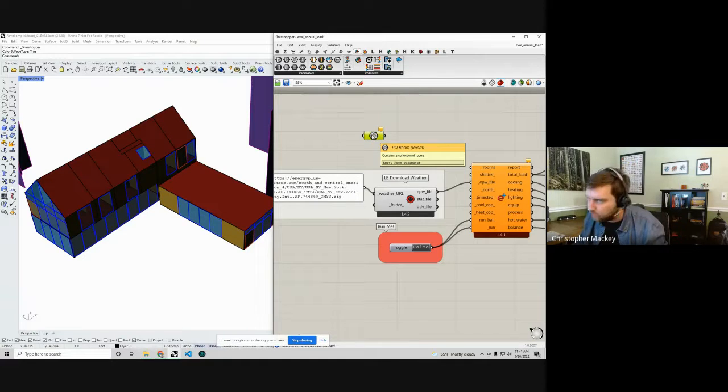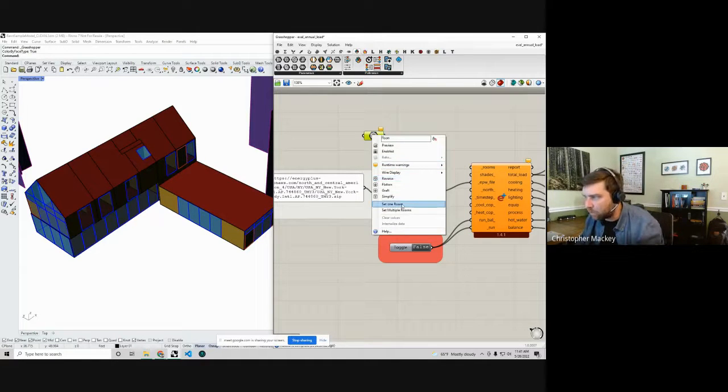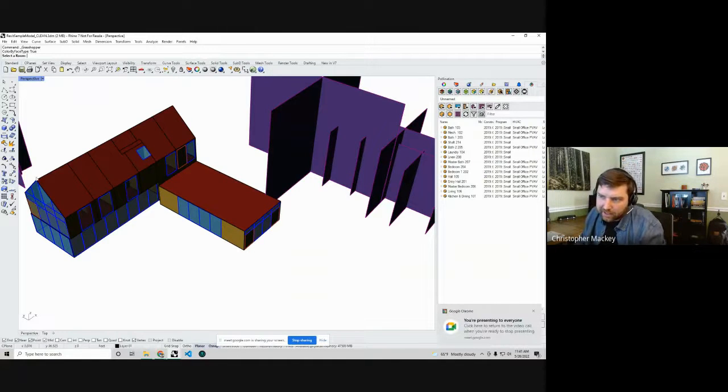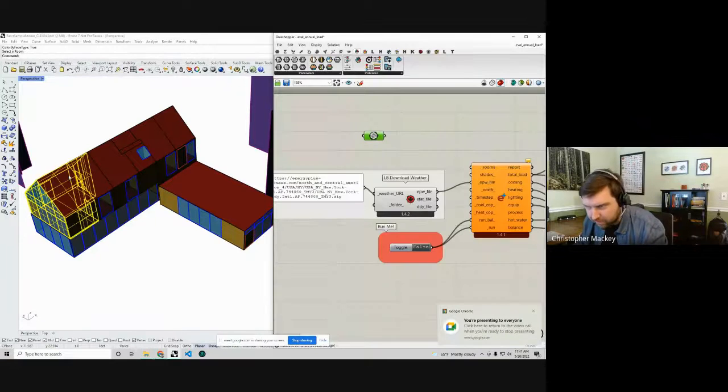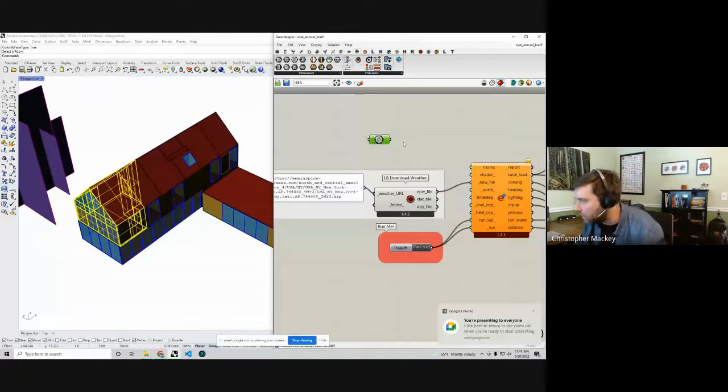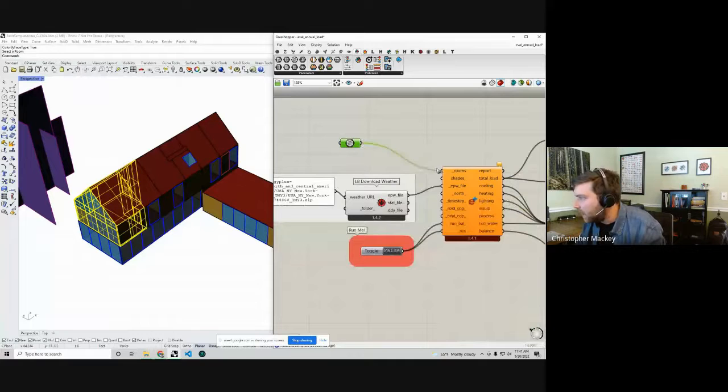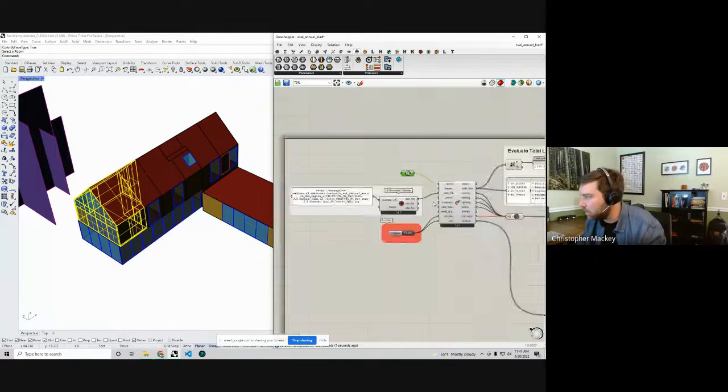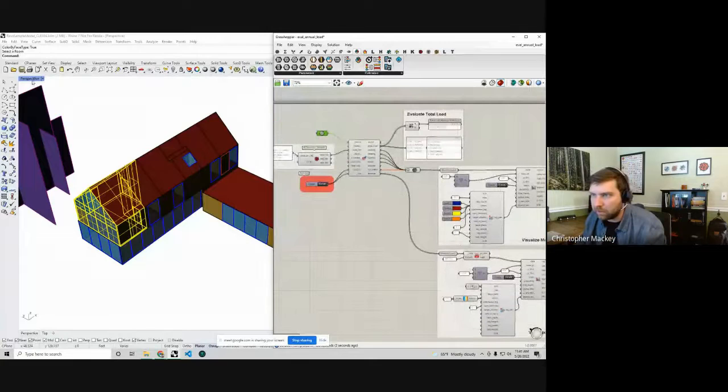Just like I did with the model, I can right click on it and say set one room. Let's say I pick this particularly glassy room that I have on the side here. That's part of an open office program, I think. And I'll connect this to this annual loads component. You guys know this component is very quick. It's made to run simulations pretty rapidly. It runs a very optimized type of EnergyPlus simulation. You see it ran. I'm getting those monthly charts there.